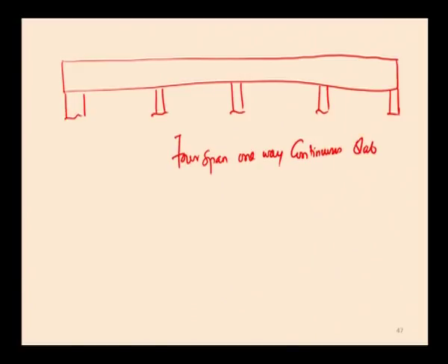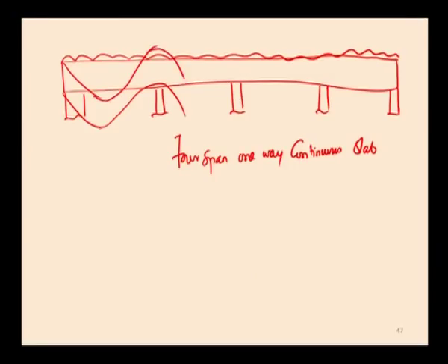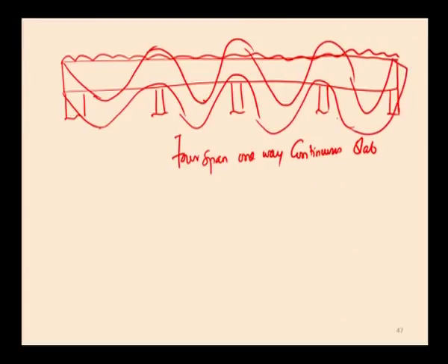I already told you that the reinforcement has to be provided depending upon the deflection nature of the structure. Now, when it is subjected to some kind of forces, this is the slab which is deflected like this. If this slab is not built into the wall at the end support, if you are going to have any wall, this slab will be deflected upwards. If you are going to construct any wall over the end support, it will deflect upward like this. We must provide the reinforcement at the top in the end support.